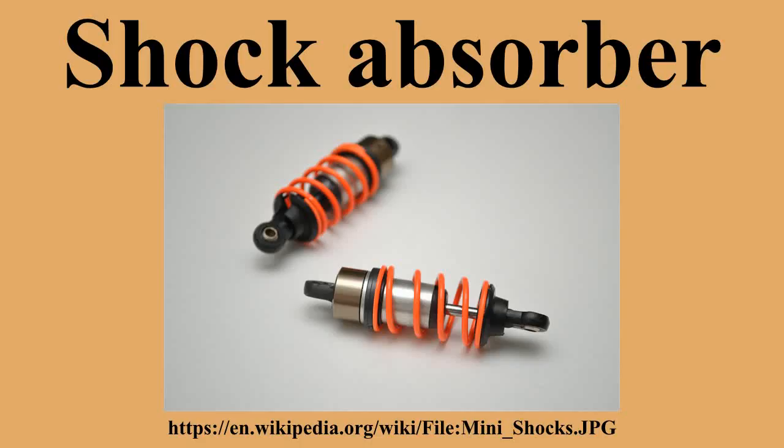An automobile shock absorber contains spring-loaded check valves and orifices to control the flow of oil through an internal piston. Design consideration: when designing or choosing a shock absorber, a key question is where that energy will go. In most shock absorbers, energy is converted to heat inside the viscous fluid.